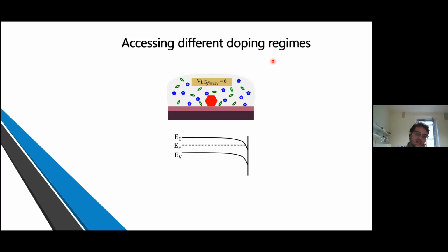I should mention that I've depicted an N-type semiconductor with a slight downward band bending. This is due to indium arsenide's native properties. Indeed, indium arsenide features Fermi-level pinning in the conduction band due to surface states, and this leads, even in undoped indium arsenide, to this downward bending and N-type behavior.